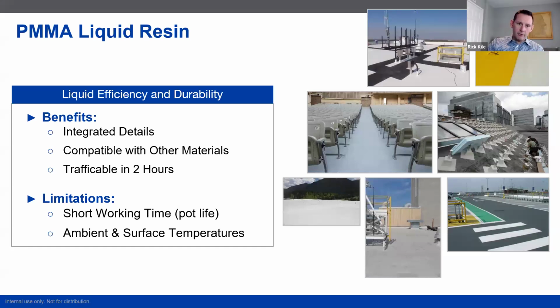Yeah, I would agree with that, and I really just wanted to reiterate the compatibility with other materials. You see it used as flashing material with hot rubber a lot, or SBS membranes, because it is UV stable, and it can be a great solution for very complex penetration and flashing details, and provide a very robust, sound solution there.